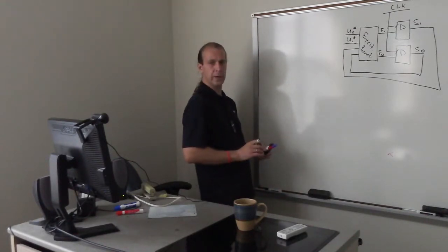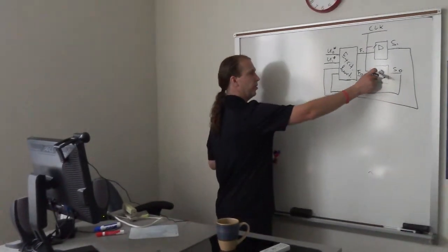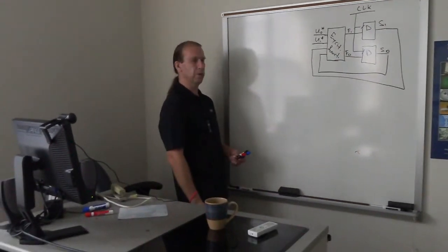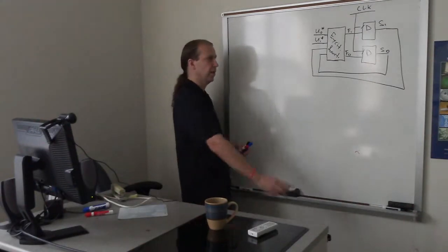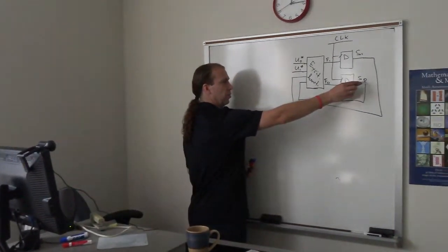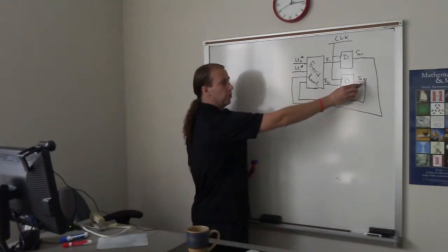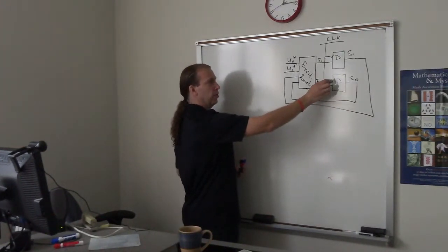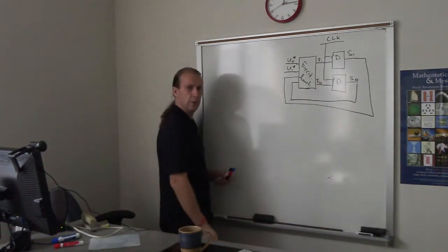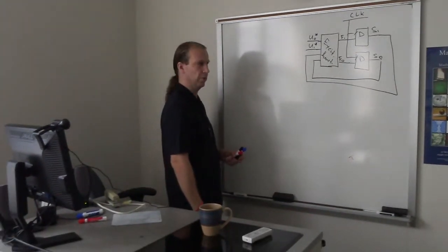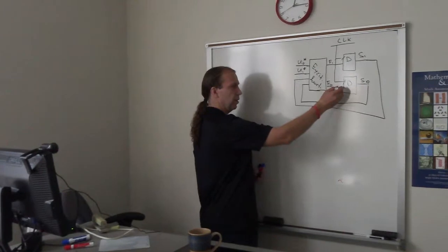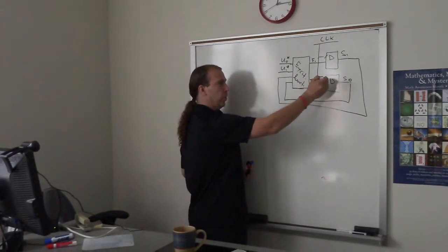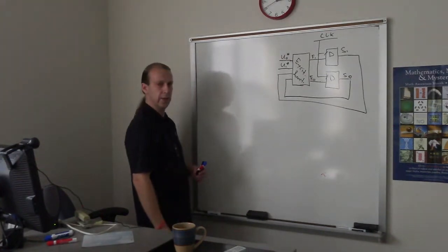And I want you to clearly understand the function of D triggers here. D trigger, in other words, is called delay trigger. It gets a certain state of the output with respect to the state of the input when a new rising edge of the clock comes in. So in other words, it reads the input data and it writes when the clock rising edge comes in.